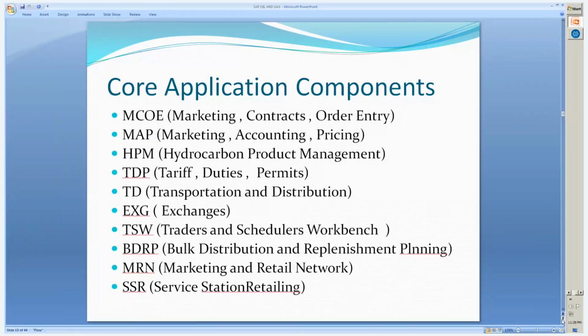we'll be able to have the conversion programs, which will help us to convert into additional quantities and also adjust the quantity according to variations in temperature. This is one of the most important requirements in oil and gas. It is not like a regular process where we are expected to deliver a certain quantity of product to the customer. From loading the product, whatever quantity, till it reaches the customer, the quantity will remain the same. But here, while loading the product and while delivering, we expect to see some kind of variation in the quantity depending on the temperature and pressure.